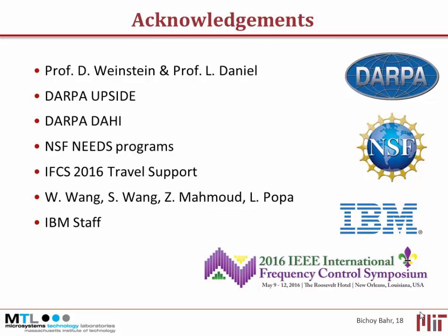Yes. So in order to avoid that, in this work in particular, my goal was to get the highest Q possible. So if my simulation finds multiple peaks, I will select the one that has the highest Q. And the second thing, I also introduce artificial damping to limit the quality factor, because the problem I saw is that lots of times I will get very high Q peaks, like 20,000, 50,000 peaks, but these peaks are artificial.